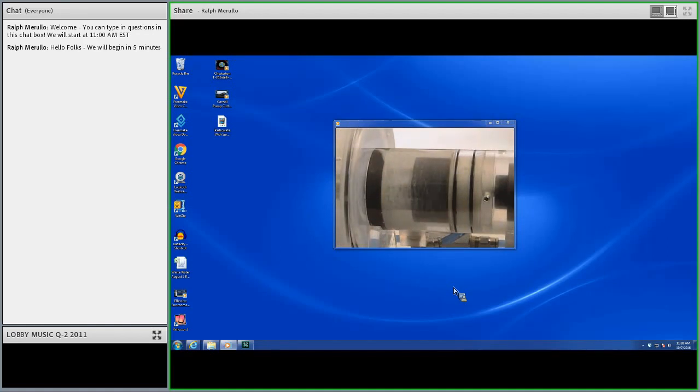So what they cleverly figured out is if you shape a device such that you take advantage of that rotation, it will act to remove the solids. So you will have clean fluid around the mechanical seal, and that's what that is demonstrating right there. It happens very quickly. Our simulations show 20, 30 seconds max for removal. This video is a lot quicker. It depends on the speed of the shaft, size of the shaft, density of the solids, all that. So in settling slurries like you find in wastewater, this is a solution, and this works.